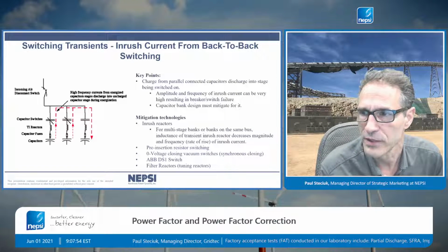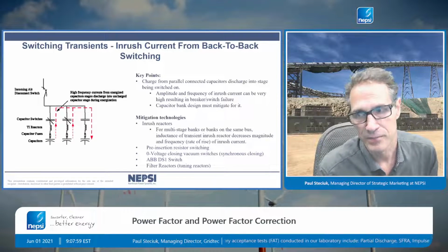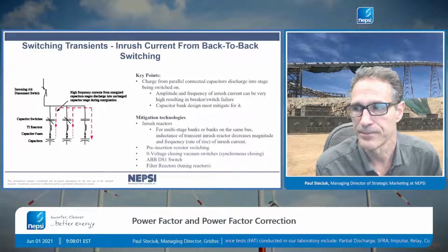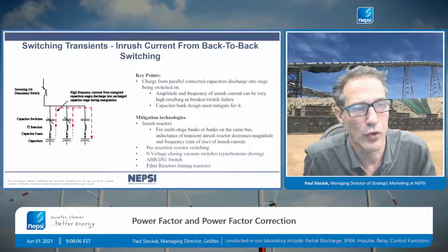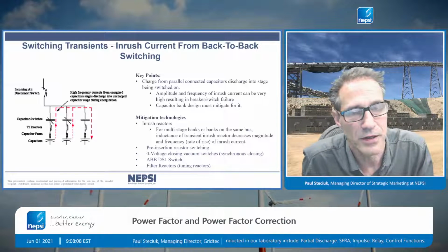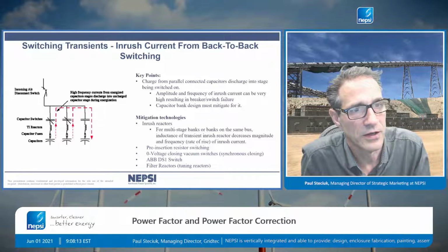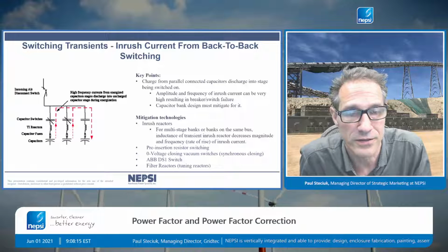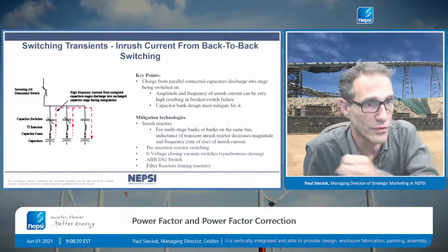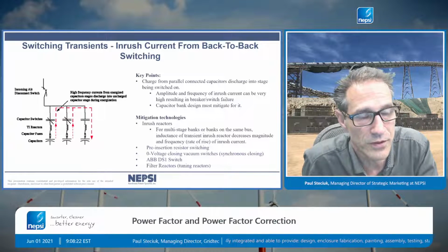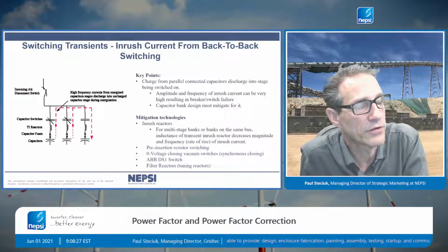There is a question from Victor. What are the critical maintenance tests and inspections to be conducted on capacitor banks and harmonic filter banks? That's a big question. In my opinion, capacitor banks are very low maintenance devices, but at least on an annual basis, you need to be checking the capacitance and making sure the capacitors are healthy. You need to be checking the insulators to make sure there's no tracking. You need to be making sure the connection points are all torqued, because loose connections can result in failure of the capacitor bank. They are the three, I would say, the biggest ones.